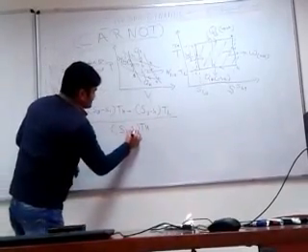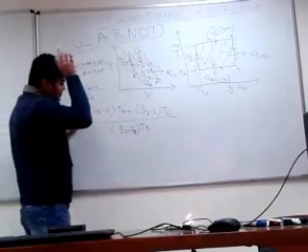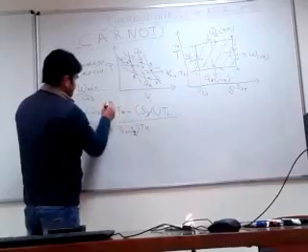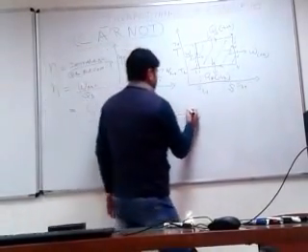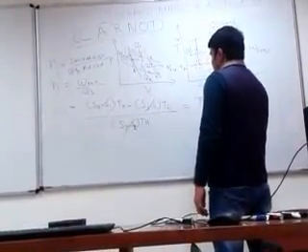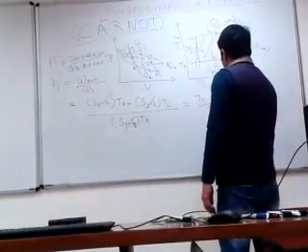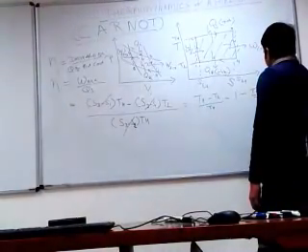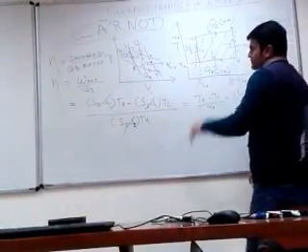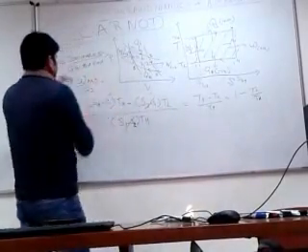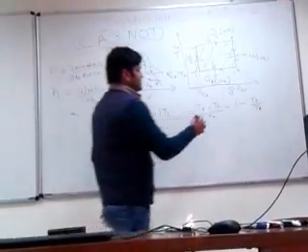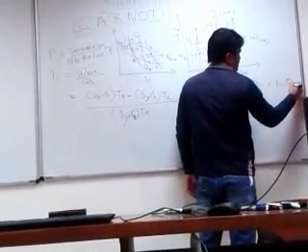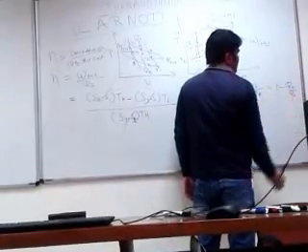The common factor in numerator and denominator, S3 minus S1, cancels out, and we are left with T higher minus T lower upon T higher, or 1 minus T lower upon T higher. In terms of heat, it equals 1 minus heat rejected upon heat supplied.